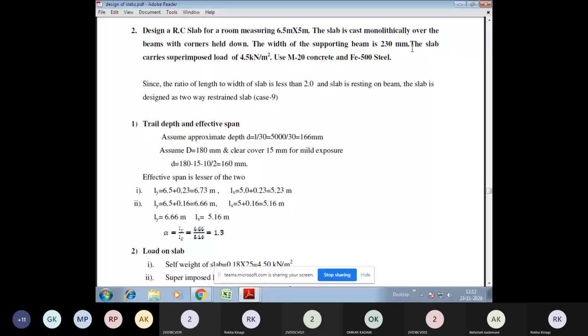Yes, here in the note for solid slabs. For two-way slabs of shorter spans up to 3.5 meter with mild steel reinforcement, the span to overall depth ratio given below may generally be assumed to satisfy vertical deflection limits for loading class up to 3 kN per meter square. For simply supported slabs, it is 35. For continuous slabs, it is 40.